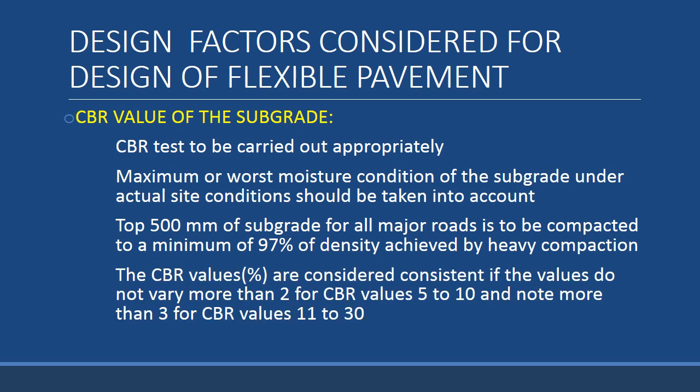Then the CBR values, which are represented in percentage, are considered consistent if the values do not vary by more than 2% for CBR values 5 to 10, and not more than 3% for CBR values 11 to 30.